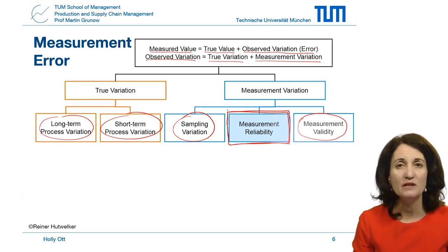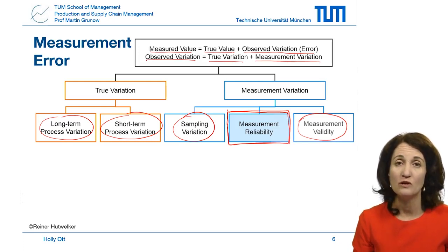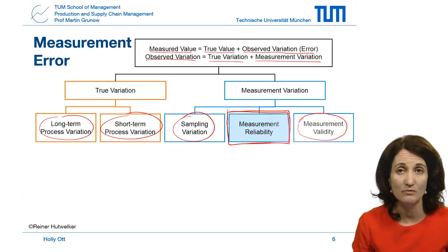The reliability of measurement data is defined by statistical properties of multiple measurements obtained from the measurement system operating on stable conditions. So in other words, with no experiment going on, we take multiple measurements using our measurement system, and then we evaluate the statistical properties and see if indeed the measurement variability is small. In order to evaluate this measurement reliability, we need to define several important measurements.